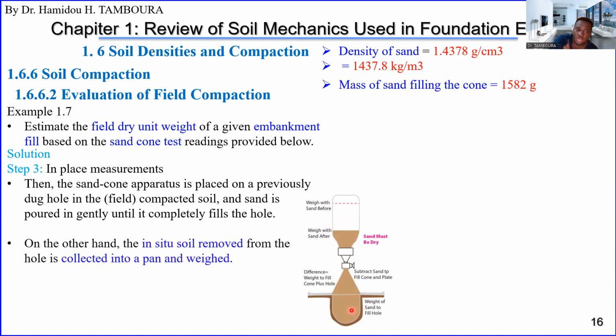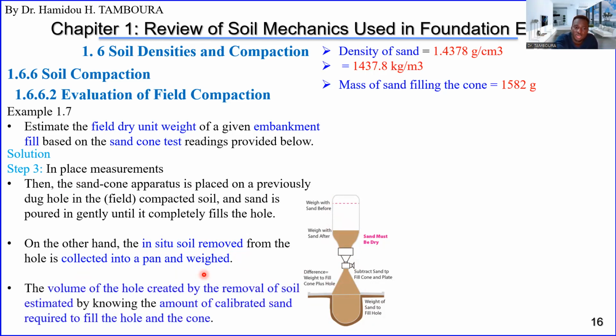Okay? Then, as I said, the in-situ soil removed from the hole is now collected and weighed. You collect it and keep it because you need to know the mass, the weight of it.